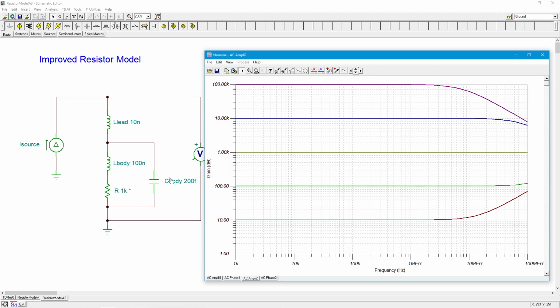So, hey, it looks like maybe the capacitor is sort of dominating in this case. Similar thing is happening with the 10K, not quite so extreme though. And then for the small values, we actually see the impedance starting to increase at high frequencies. So that appears to be the inductance dominating in that case, right? You see just a little bit of a rise for the 100, but there's a really obvious rise for the 10 ohm.